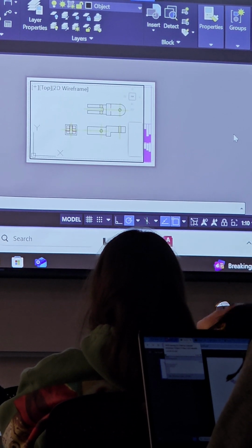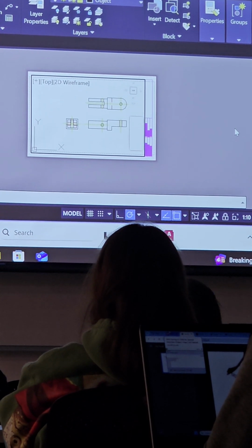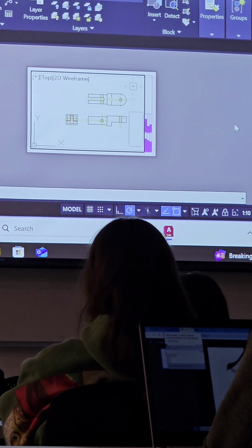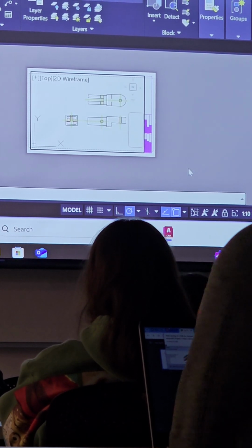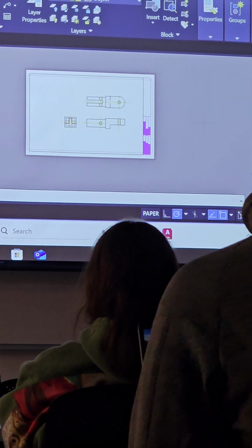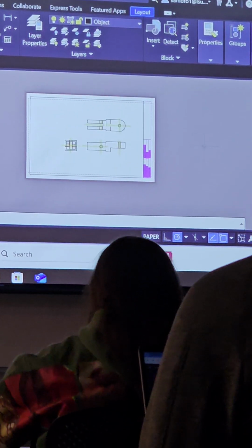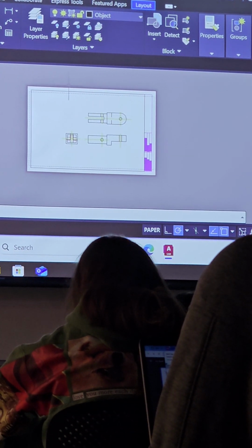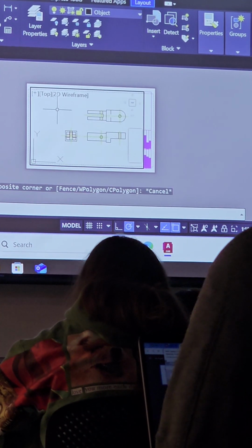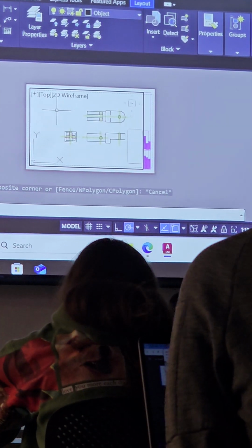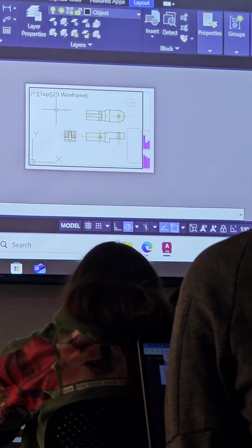If I told them it was 1 over 0.12, that's sort of like 1/8, but not exactly. So logical scale. When I open your drawing, I'm going to go to this layout tab. I'm going to look at this view, and I'm going to double click inside this space, and I'm going to look down at the bottom here, and this better be something logical, right?